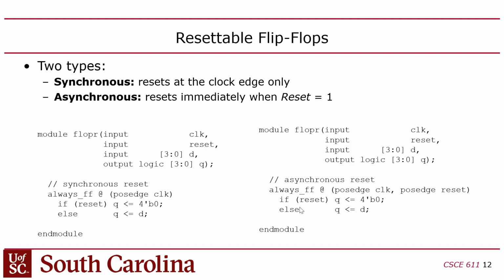when you get your branch and jump instructions, it's important to have it, because if the program counter comes up in a random value, you might end up in a part of your program where you're in an infinite loop and you never roll back to 0, right? But right now, when you don't have branch and jump instructions, then you're guaranteed to eventually get back to 0, right? Because it's just counting up by 1. You guys with me? Okay.